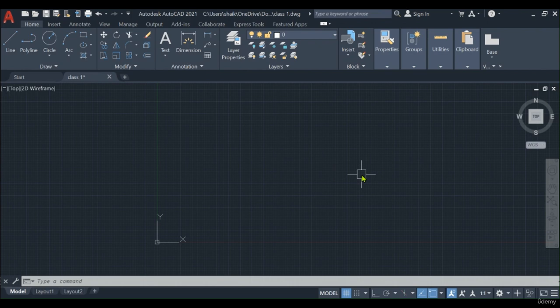If you zoom out or zoom in on things, for that we need to use the limits command, where we set the drawing area. We are limiting the drawing area. Once we set the drawing area, we are going to draw only within that area, so that it will be easy for us while taking printouts, and easy while converting into scales, or while setting the scale.